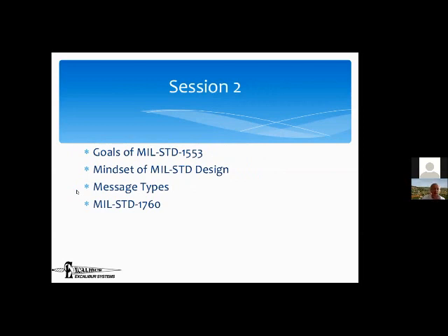Okay, so that takes care of the general introduction to avionics buses. Now we're going to go into more detail on 1553 itself, and we'll start with what the design goals were, and then talk about the mindset. I don't talk about the mindset in any of the other bus courses that I give, but in 1553 it's quite important. And then message types, which is the key to understanding the communication. And we'll talk a little about MIL-STD-1760, which is a subset of 1553. It just adds a few requirements.